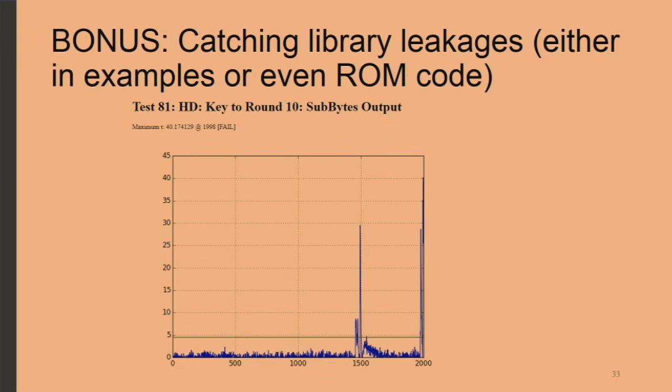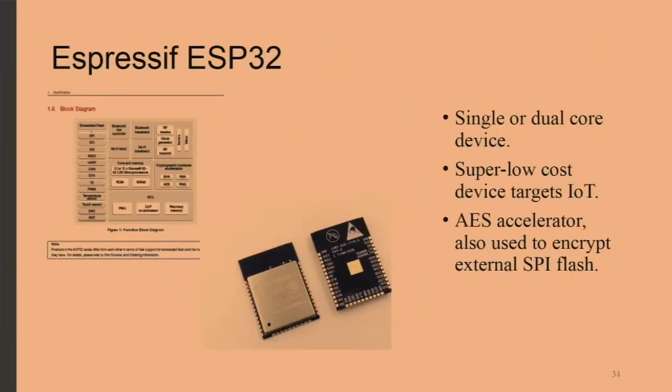So some of these detections found that, which could be really useful in a real product where if you're just trying to recover a key, it's not the actual hardware accelerator causing the leakage, but some bad usage of it really made the side channel leakage a lot worse.